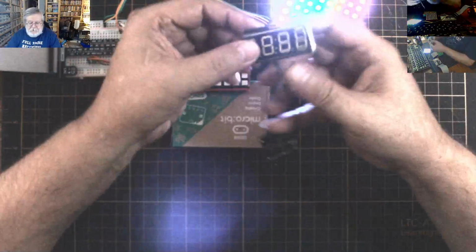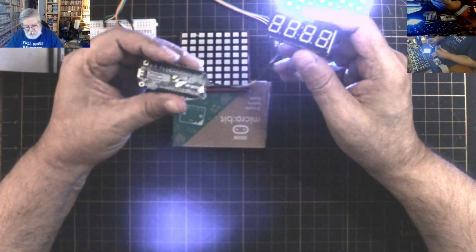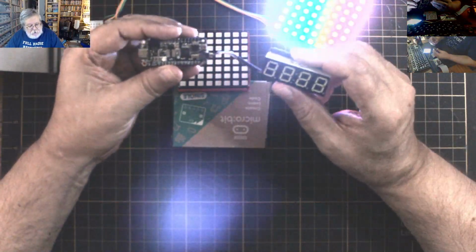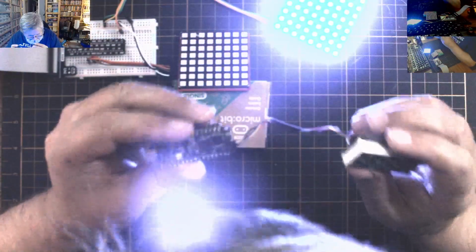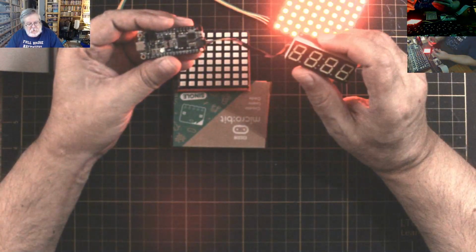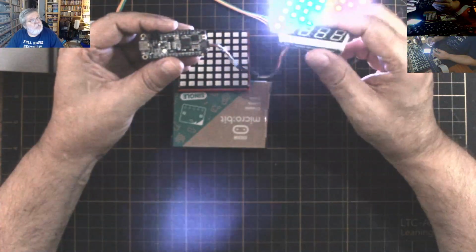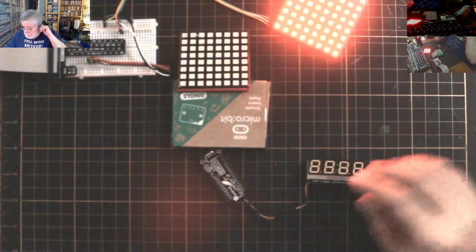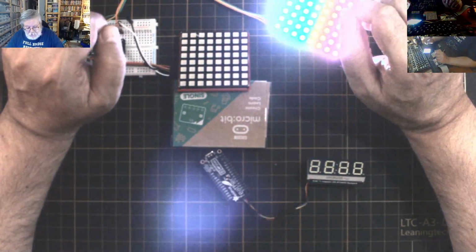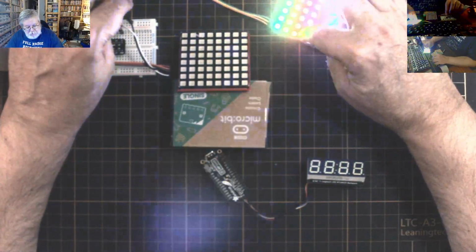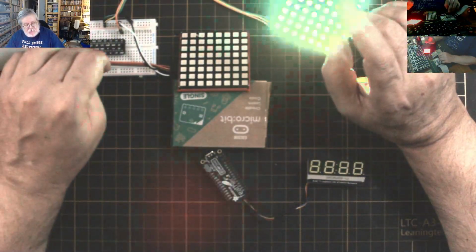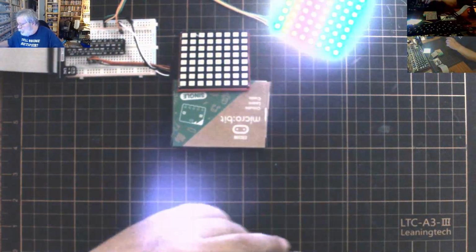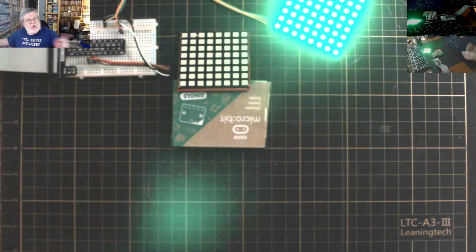So here's, for example, a digit LCD, and I've just tacked it through the I2C bus to a feather. This is an RP2040 feather? Yes. And it's easy as pie to make these do digits and whatever. And once you get into I2C, another limitation is removed. On SPI stuff, only one device can be on that SPI side. That's it. If you need more SPI devices hooked up, you have to have more SPI buses.